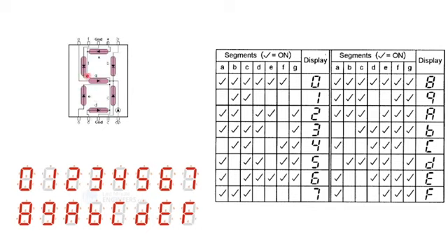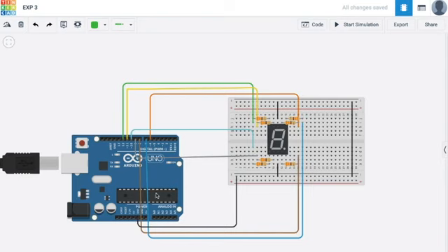To make the power dissipation proper, I think they have made this grouping, so these segment LEDs were connected to this ground. Here, in the internal circuit, if you see, you have two grounds on both sides. The middle pin is the common cathode or ground, so that has to be connected to the ground pin of our Arduino.